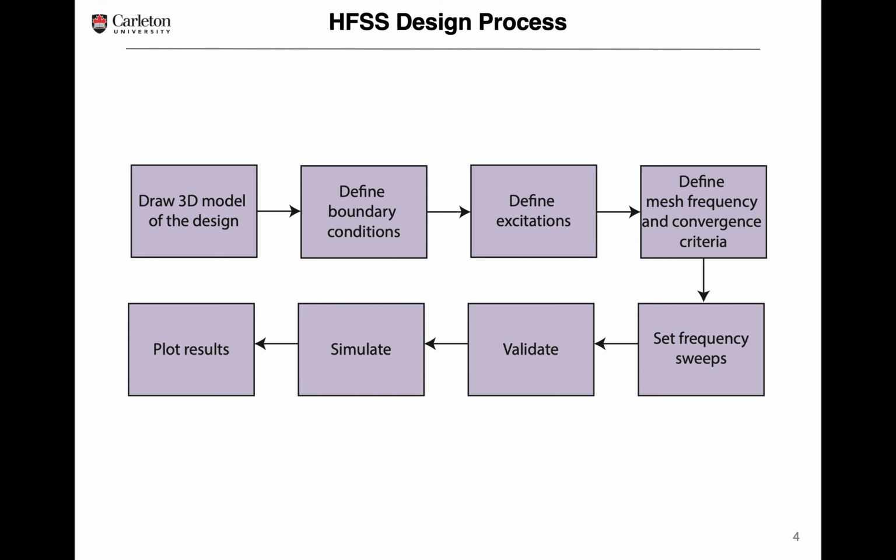And then the fourth step is to define a solution setup and the frequency sweep and the convergence criteria. So you're telling HFSS what frequency you want the solution to be solved at, and what convergence criteria that you find acceptable. And if you want to look at a frequency sweep, you're going to tell the software, I want to see the results from this frequency to that frequency. You're also going to tell it what type of sweep, if you're interested in just viewing maybe just the S parameters, or if you want to view a visual of the fields inside the structure. So this would be defined in the solution setup.